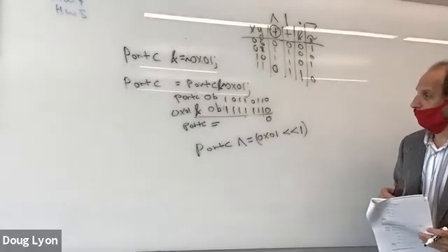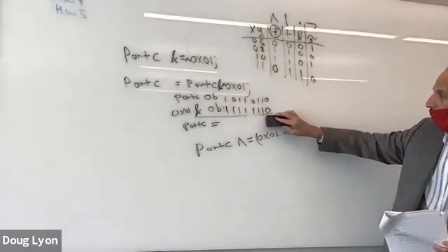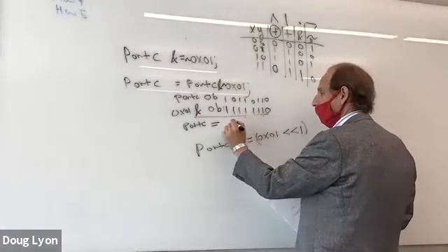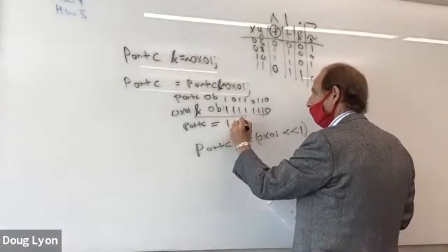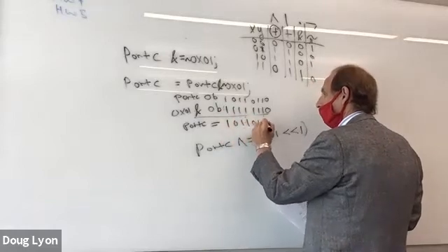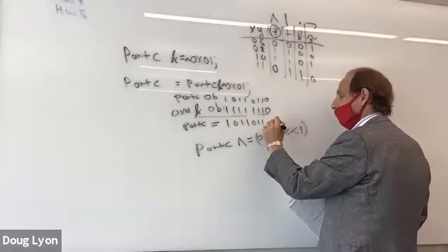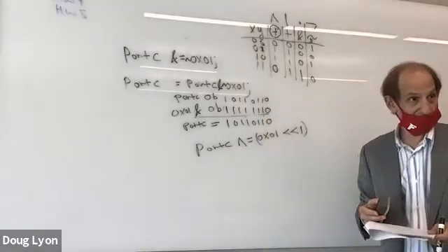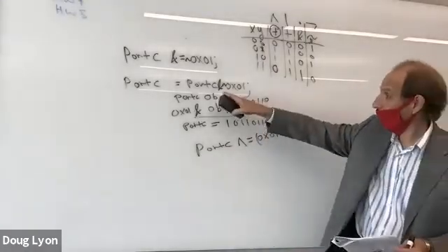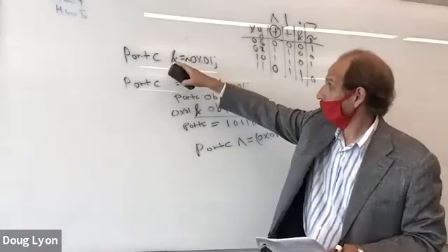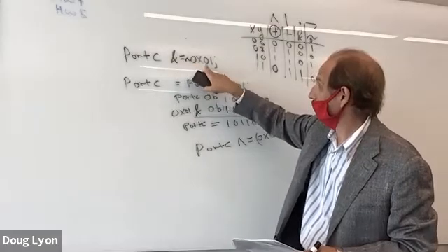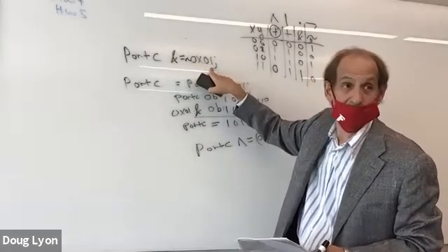So now, what's the output look like? And the answer is, everything in the most significant bits will be preserved, but the least significant bit will be cleared. So now we've cleared the least significant bit. So this little idiom, well, I guess you write this one: ampersand equals tilde 0x01 clears the least significant bit.